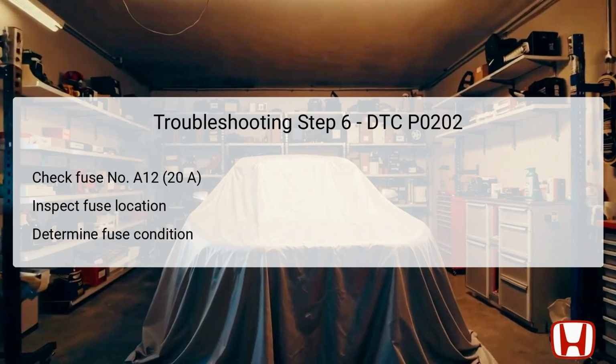However, if the fuse is found to be blown or damaged, it will need to be replaced, and the subsequent wiring associated with the fuse should be checked for potential short circuits. This step is a vital diagnostic point, as a blown fuse can disrupt the entire injector circuit.